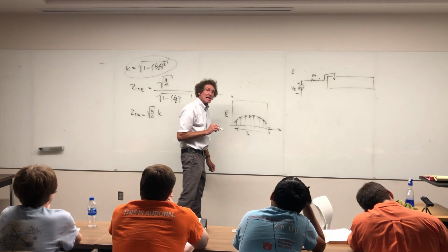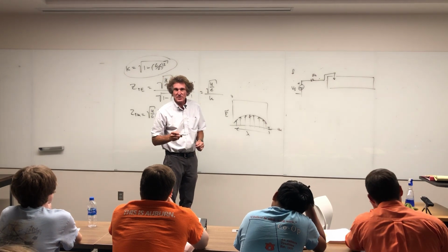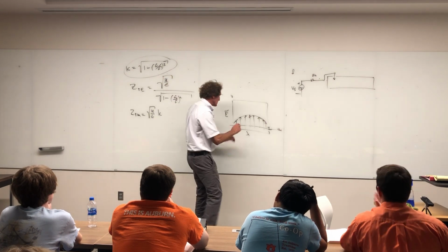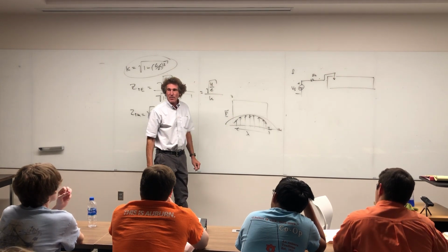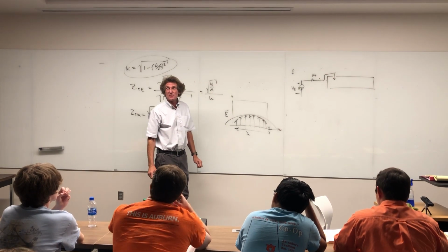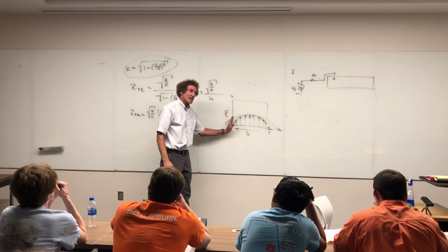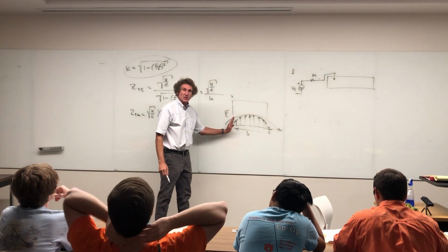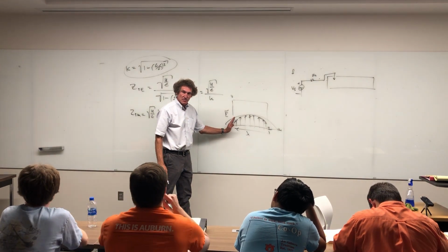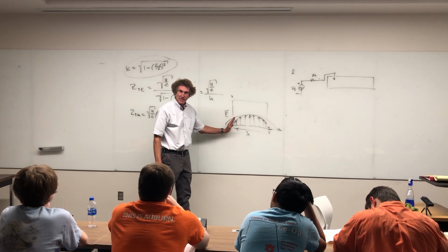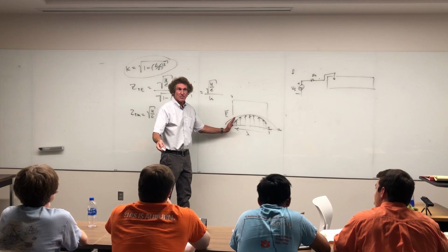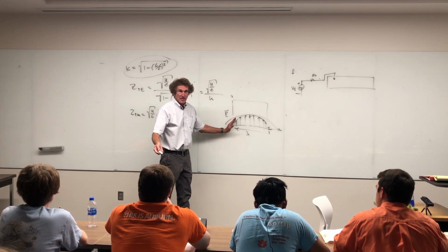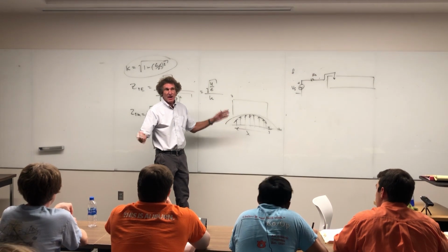Now, what happens at cutoff, just so you can get an appreciation of this, what you try to do is stick in a wave that doesn't fit. You would like that one to go in as a 1-0, but it doesn't fit. You see how these sides short that out? So all that energy is shorted out. It's called an evanescent mode, and I'll speak more on that in a bit. I'm trying to give you an appreciation for this without doing the hardcore math. Do you all see what I'm talking about? That's why waveguides only pass higher frequencies.